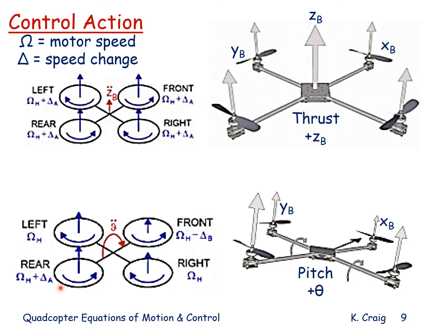We see here motor 3's speed is increased, motor 1's speed is decreased, and we have a positive angular acceleration in the pitch angle theta.